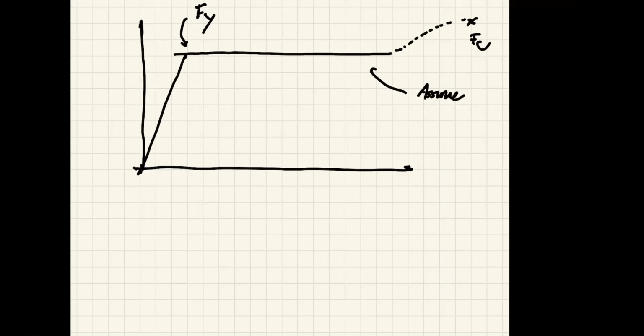Actually, they use the word plateau. Okay, and when you have the situation where the stress doesn't increase but the strain keeps going like this, that is plastic behavior. You don't have to increase the force, you just have the deformation going, so that's plastic.